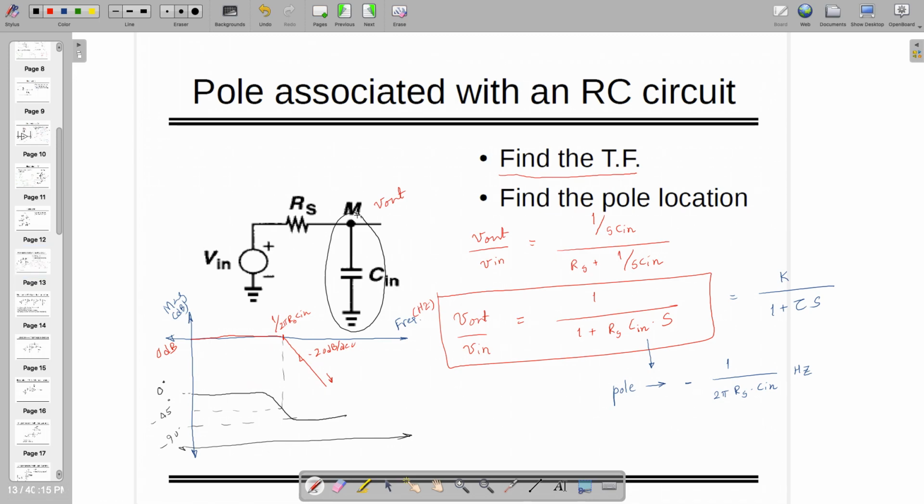So what you have to do is find out the resistance associated with that capacitor, because here you can see that the pole location depends on R and C. So it's 1 by RC if I don't consider 2 pi, and if I'm interested in radian per second, I can do this. So I need two things: one is the resistance and one is the capacitance. The technique says to find out the effective number of capacitances. So that many capacitances will give you that many poles. In this case, we have only one effective capacitance.